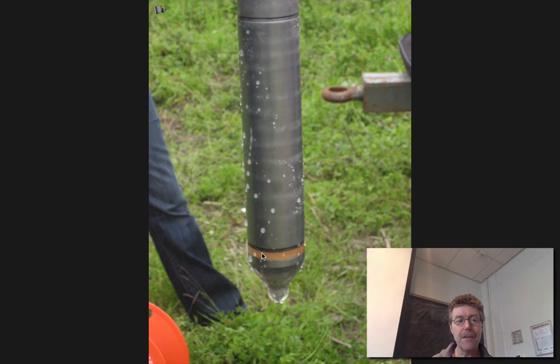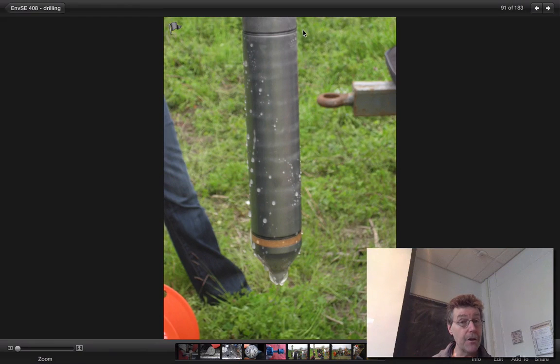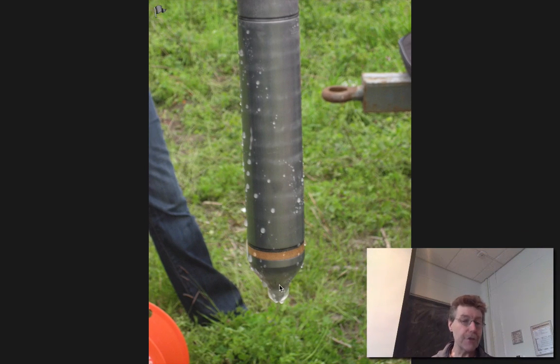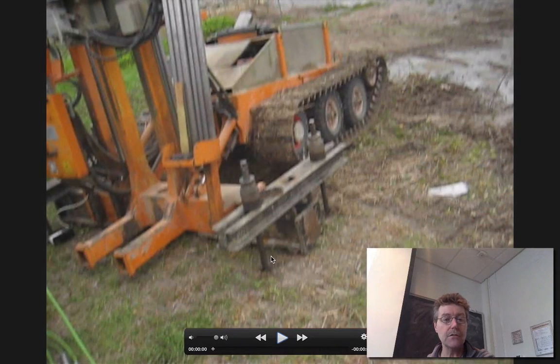This is the pore pressure measuring part. This is a load cell behind here. This is another load cell here. It's saturated with silicone oil, so that there's no air in it. And then once it's saturated and de-aired, it's covered with a condom in this particular case, as you can see. And that's just physically pushed into the ground. As it goes into the ground, this condom just gets ripped off as it abrades against the ground, but it means that when it goes into the ground, it actually is saturated, so you don't get strange results.